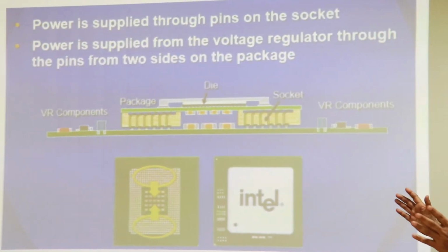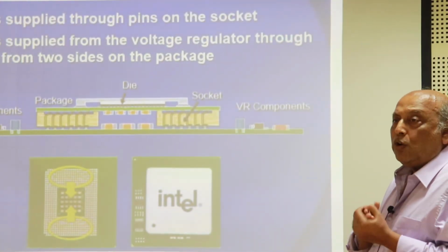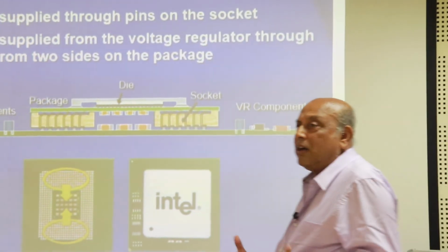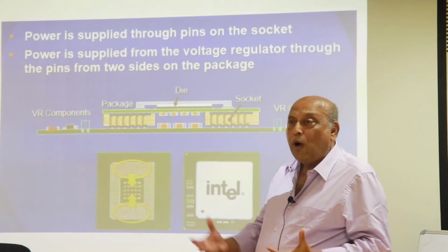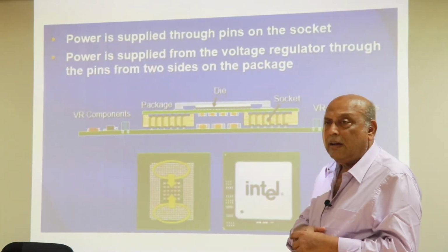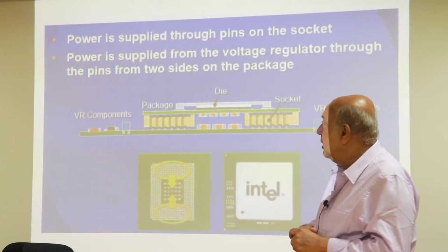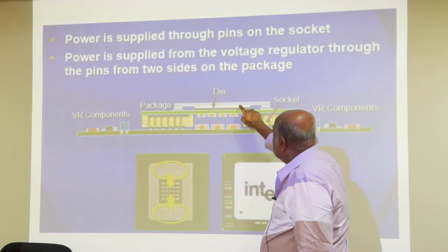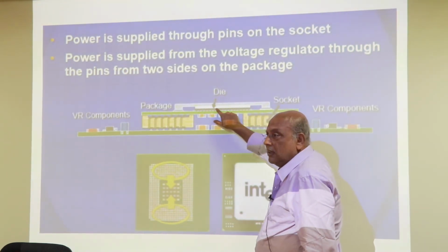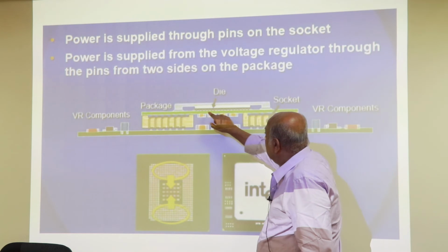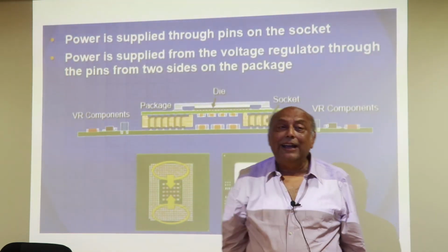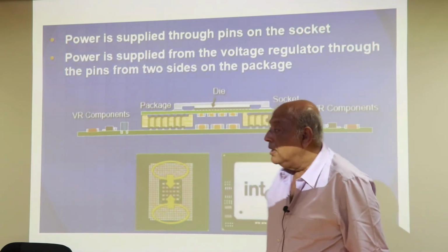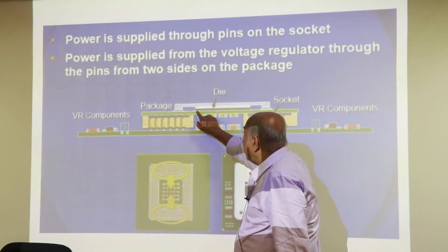Now this is the way the general picture looks like. You cannot sit with your power supply on the top of a chip, as I said. But you still need 1.6 picohenry kind of number, right? So this is the die, silicon die. You see this is silicon. You see this? These are called solder balls, discovered by IBM in 1962. They have a 150 micron